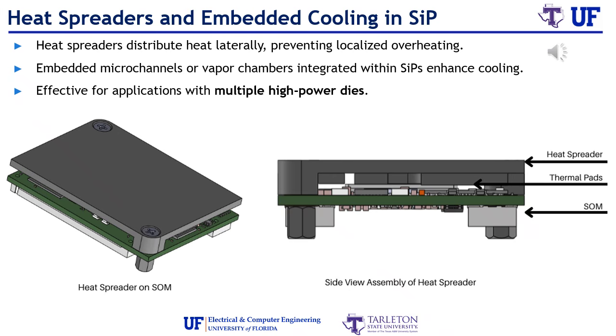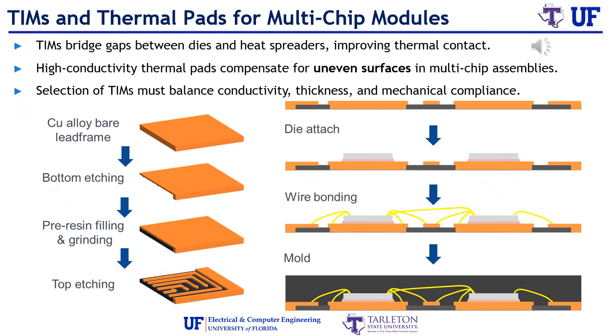Thermal interface materials (TIMs) may look like simple paste or pads, but they are crucial. Even smooth-looking metal surfaces have microscopic roughness that traps air, which is a poor thermal conductor. TIMs fill those gaps with a thermally conductive medium, greatly reducing contact resistance. Engineers choose TIMs based on thermal conductivity, but also viscosity, mechanical compliance, pump-out resistance, curing behavior, and long-term stability.